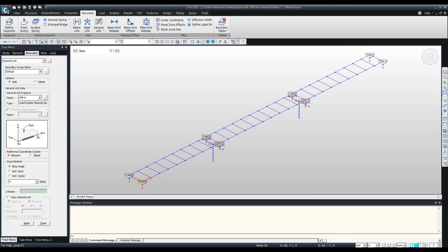So what I'll do now is go into the next step, which will be to go over all of your mass inputs. Some important things to remember is that there are three types of masses that can be defined: structure mass, nodal mass, and load to mass. Detailed applications of each type of mass are explained in the online manual.